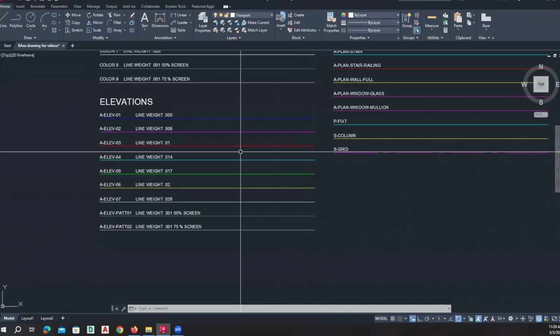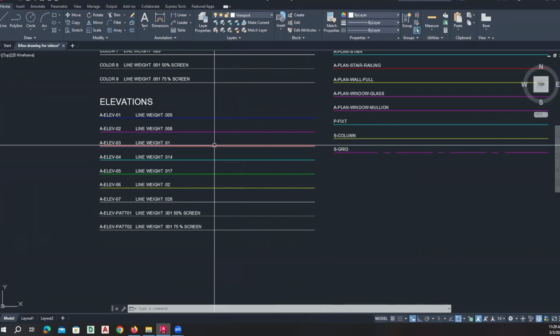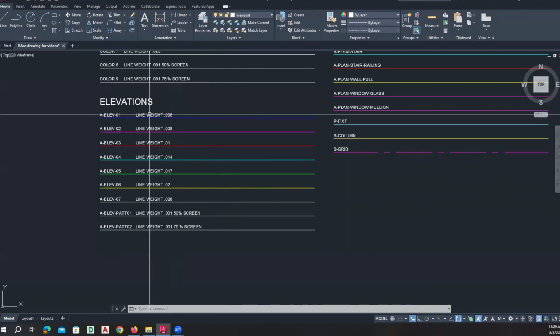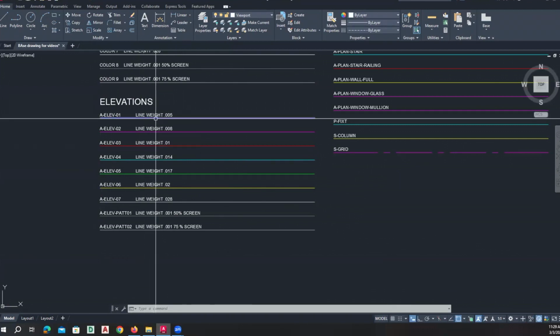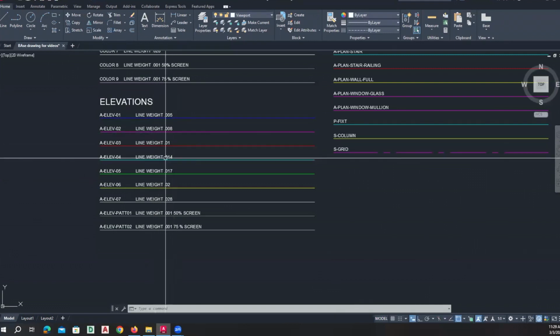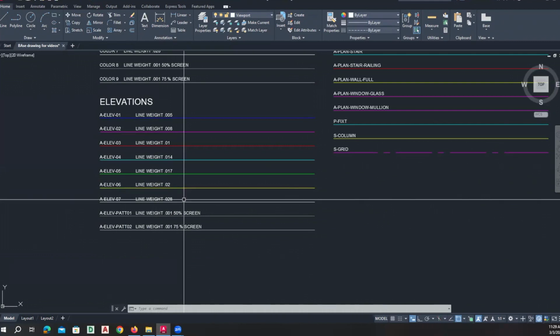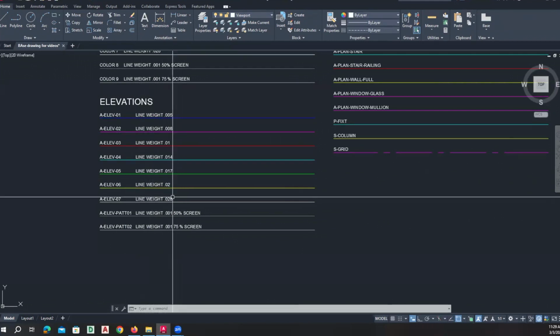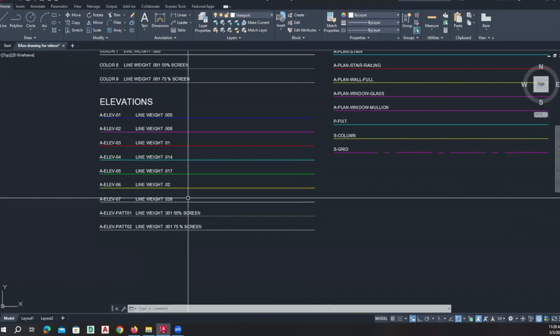Okay, so if I was drawing a piece of furniture that had two pieces of furniture in my drawing, and one was really far away, I would draw that on this layer. If I had the same piece of furniture that was much closer to me, I might draw that in a line weight of like 0.014. If I cut through a wall, right, or cut through an object, I would be drawing that with the heaviest line weight to make sure that it's clear that I'm cutting through it.